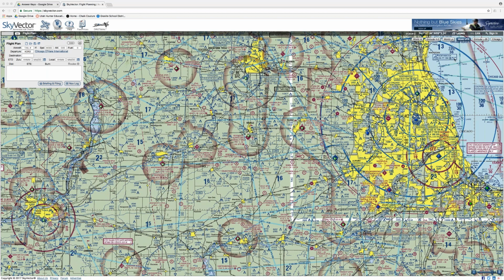So yeah, in Class B would be 250 or below 10,000 feet, and that's the question that you're going to get asked. We won't ask you about the underlying Class B or Class C airspace below 2,500 feet AGL. Like, we're not going to ask you those ones. The important one to remember is under 10,000 feet, the speed limit's 250 knots. Okay? All right. And that one is on the ADX as well.